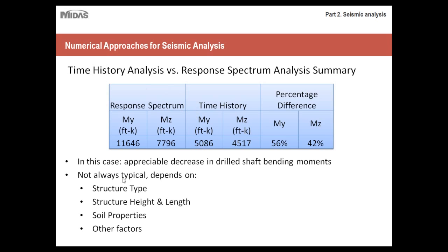Now this isn't always typical. Just keep in mind this is just one experiment, one case study. As Benjamin made sure to point out, it really depends on the structure type, the structure height and length, soil properties, and various other factors. But one of the main things to remember about time history analysis is that it's used for higher level projects, and for projects that reside in very high seismic zones.